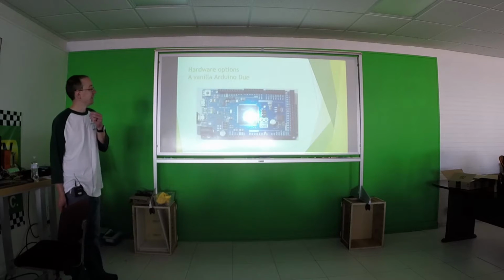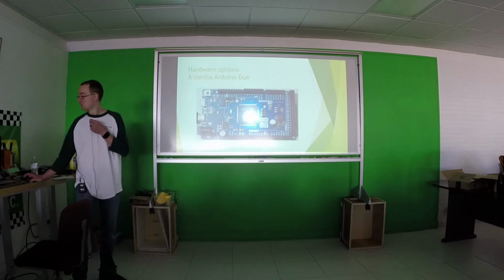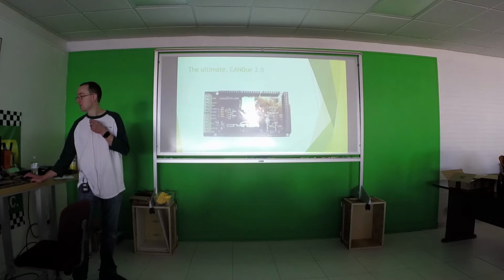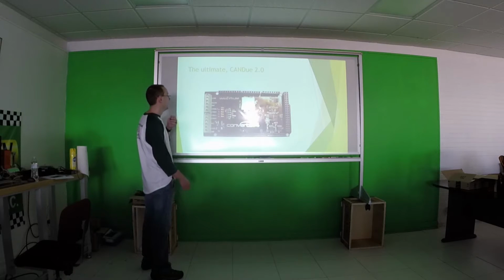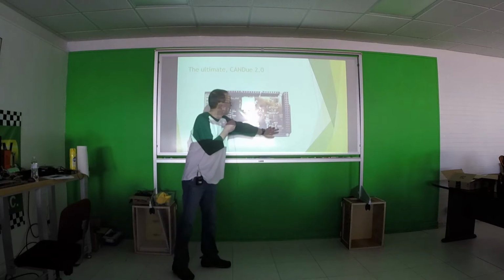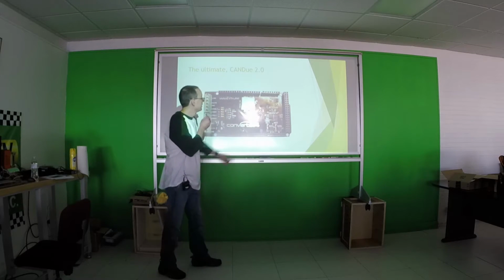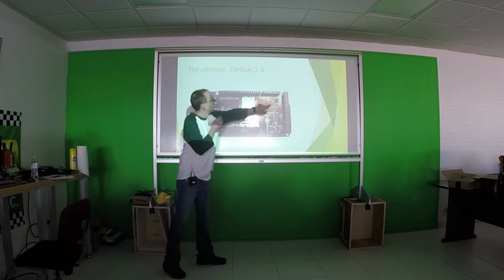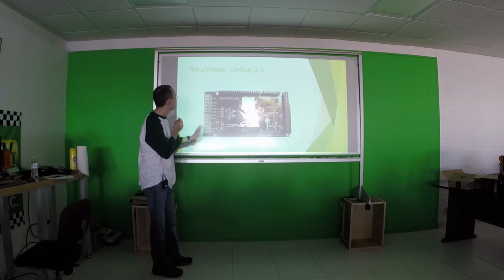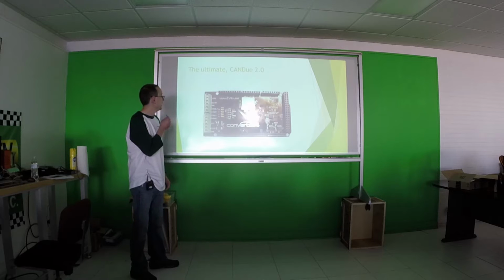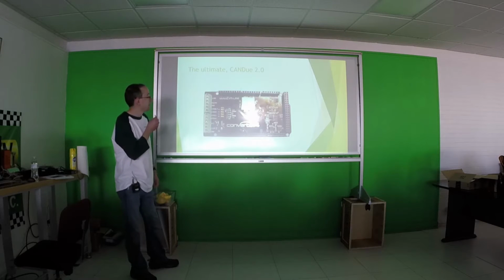They have pins, but as he mentioned, there's no transceiver on that board, so it's not really possible to directly use that. So we've made this board. It's a shield that plugs over top of the other one, and he showed how there's transceivers. There's the two transceivers right here for the CAN bus. There's a single wire transceiver here, the EEPROM up there, and switchable termination. So that pretty much adds everything you could ever really hope for in a hardware tool for capturing. We have two CAN buses, 1 and 2, the NTC temperature input, single wire CAN. So everything is on that one board.